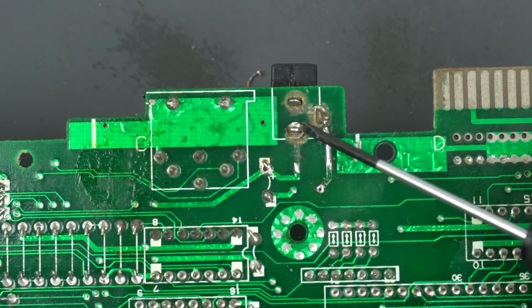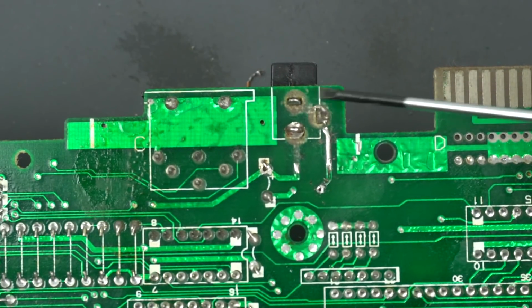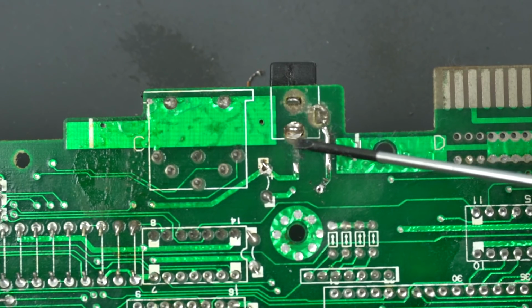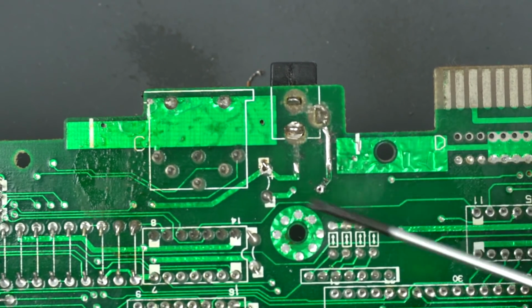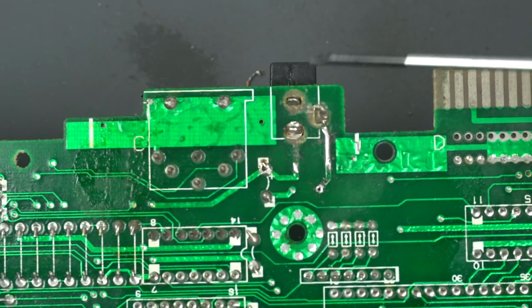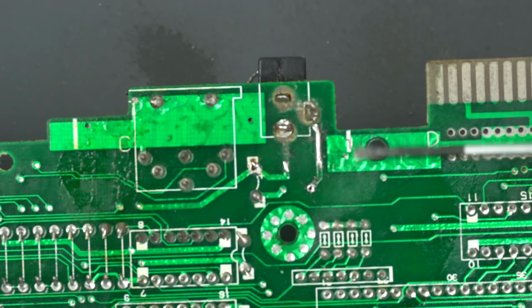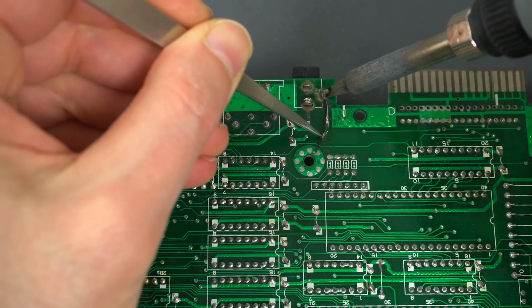You can see how that track, and that's the 5 volts coming from the power supply, is broken there. Oh, I see. The pads were broken. Even this one. Yeah, this pad is lifted. Look at that. So that's why they had to do this botch job in there. So somebody probably replaced this because there was probably some dry solder joint. I'm still wondering why it didn't work the second time we tried it.